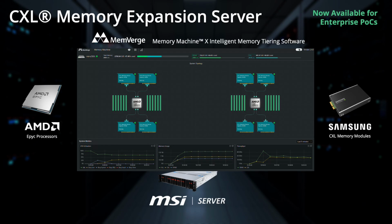To provide a concrete example of a real server using CXL and Memory Machine, this is the new MSI S2301 server. You can see from the system topology that it has two AMD Genoa CPUs and 8 Samsung E3.S CXL memory expander devices, and these are installed in the front of the server, just like NVMe drives. So with 1 terabyte of CXL and 768 gig of DRAM, this system has 1.7 terabytes of usable memory. Now the system itself supports up to 8 terabytes of memory, so that would be 6 terabytes of DRAM and 2 terabytes of CXL.